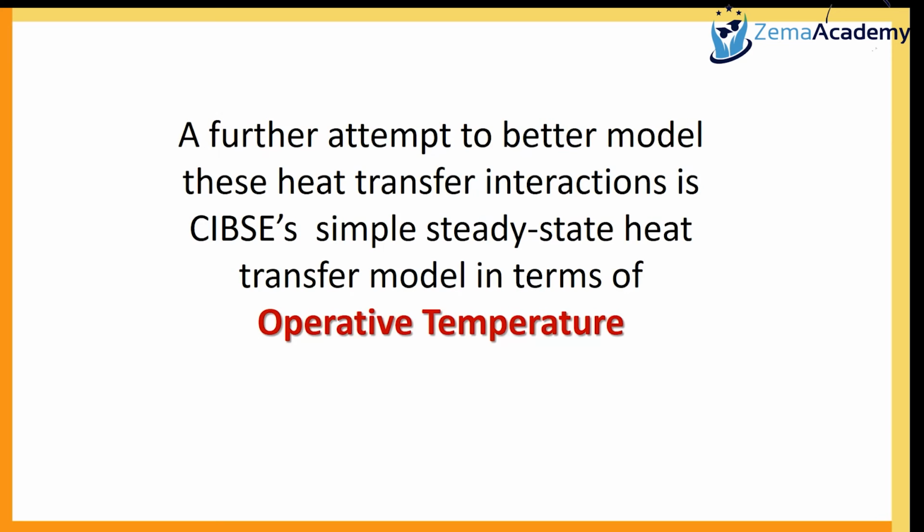But now our aim is, rather than looking at that temperature difference in terms of inside environmental temperature, we want to replace that inside environmental temperature with a new temperature. Why? I will make this clear in the next slide. That new temperature that will replace the TEI is operative temperature. This operative temperature is written as T with a subscript C.